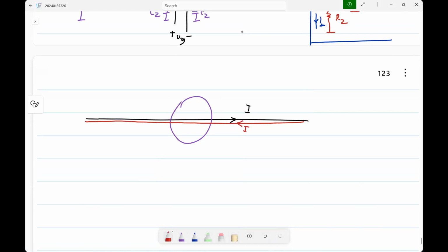You know from all those integral formulas that what matters is the total current enclosed. So if you have wires almost coincident and they are carrying equal and opposite currents, then the magnetic fields will cancel out. That's why, when you have a wire going this way and a return path, they should be very close to each other.